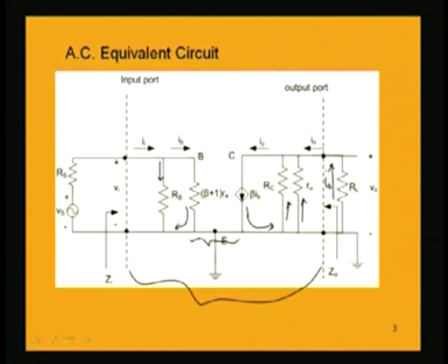Now, again if we replace what is I0, if we look back into the circuit, what is I0? I0 is that part of the current IC which is flowing through this resistance RL, because if we look into this output side, the current source is beta times IB, which is equal to IC. This current is flowing in this output side, and this current has three parts.